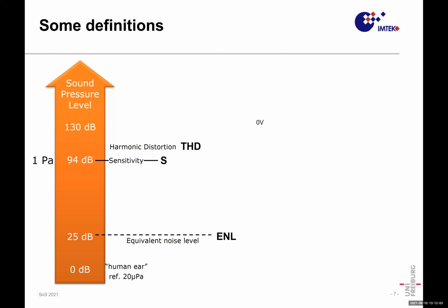And okay, we also give a total harmonic distortion at 1 Pascal, which is giving a number for linearity of your device. It should be small, of course, at 94 dB SPL. And somewhere we reach a limit of sound pressure levels where the total harmonic distortion gets high.